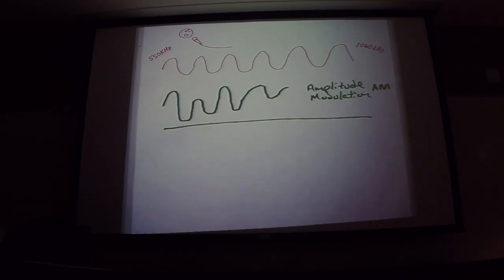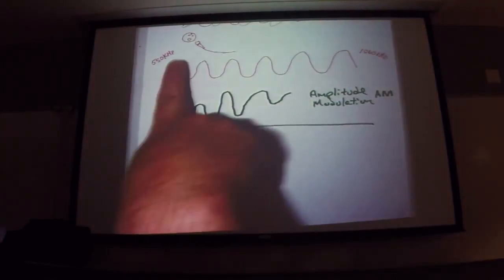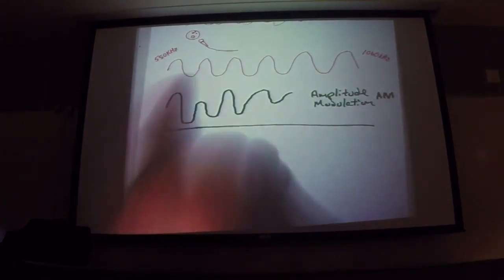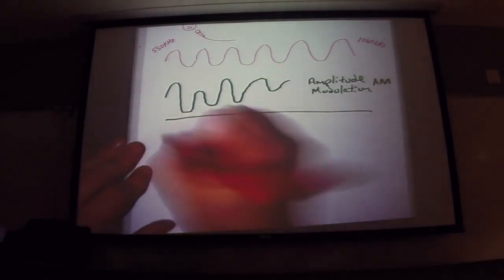because the order of your sound wave, whatever sound wave, 10,000, 20,000, which is okay because you're comparing it to megahertz, millions of hertz, which is why, again, you won't want to modify that frequency by some thousand of hertz because, well, it's going to shift it on the dial. If you try to do that, it's just not going to work. That's why you have to use a very large frequency to do your frequency modulation. So that's the second way of doing it, okay? Is to use the frequency modulation.